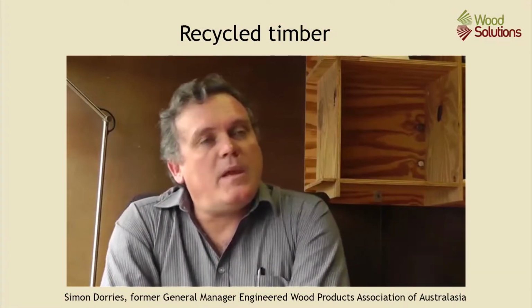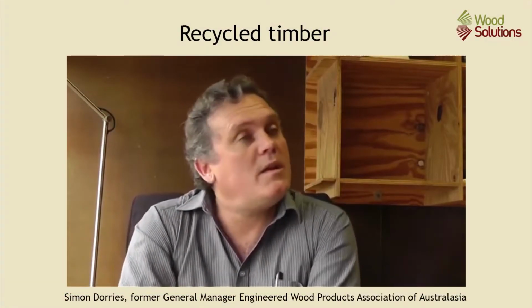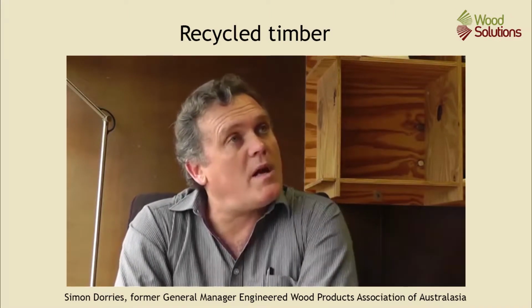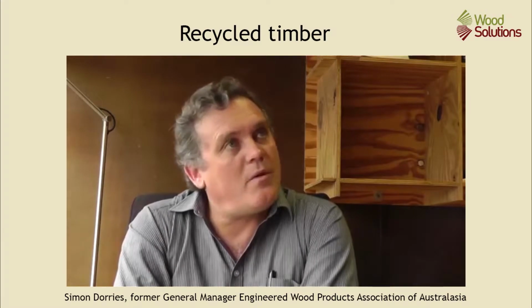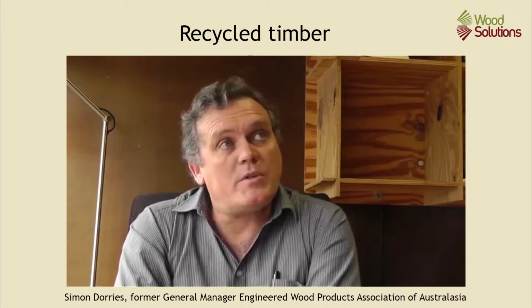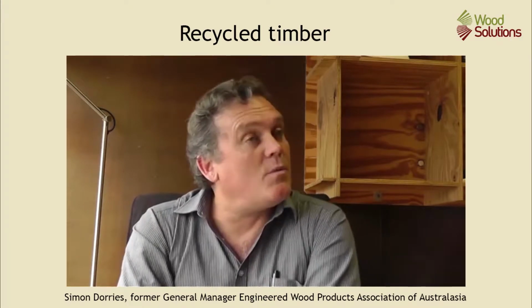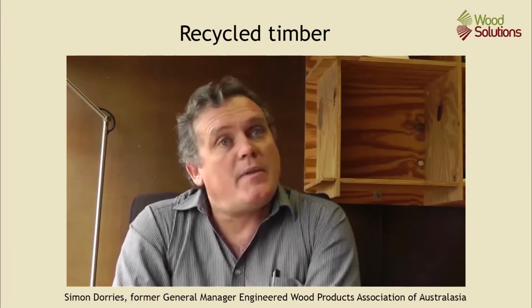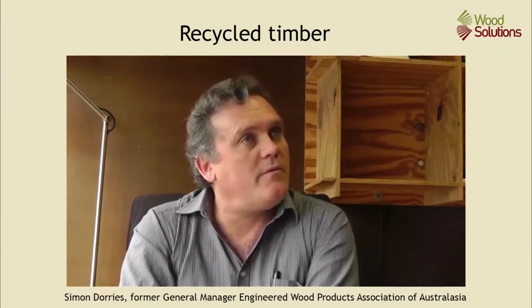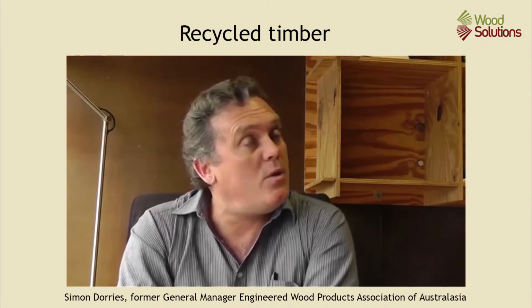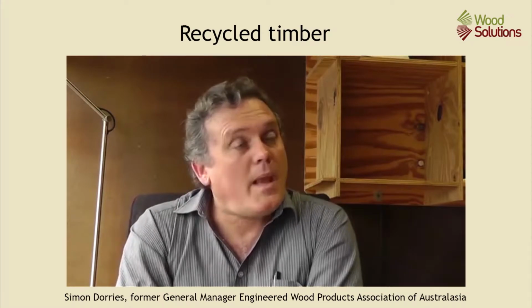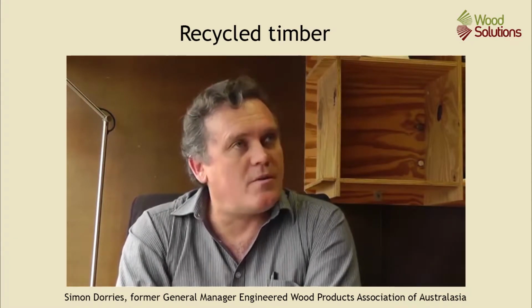Now the other critical aspect with plywood in particular is surface quality. So under Australian standards there are 4 veneer grades. There's an A grade, a B grade, a C grade and a D grade. An A grade is an appearance grade that's almost perfect. It's the Rolls-Royce of veneers. That's suitable for clear finishing and is often used in very expensive timber veneers and indoor panelling, doors and very expensive furniture. A B grade is a paint grade.